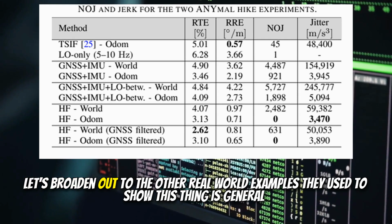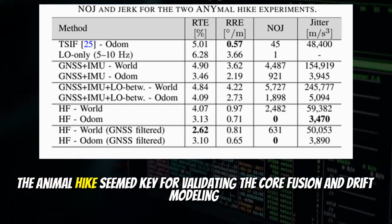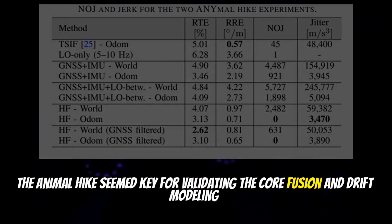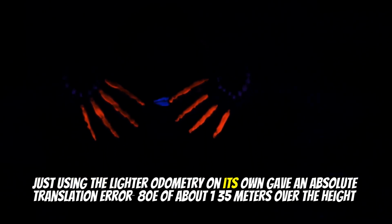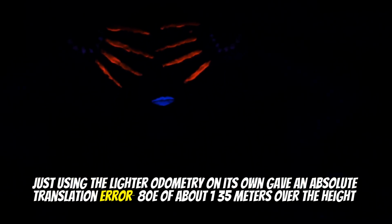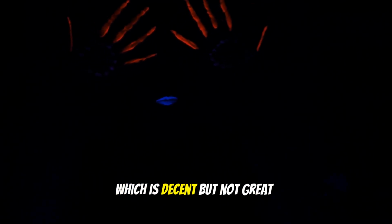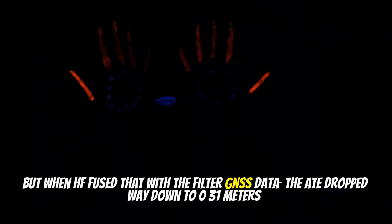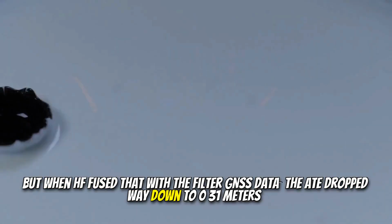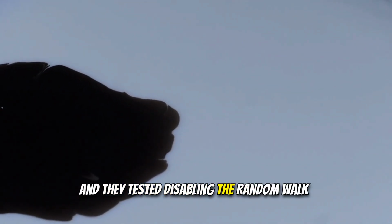Yeah. Let's broaden out to the other real-world examples they use to show this thing is general. The animal hike seemed key for validating the core fusion and drift modeling. Absolutely. Just using the LiDAR odometry on its own gave an absolute translation error, ATE, of about 1.35 meters over the hike. Which is decent, but not great. Right. But when HF fused that with the filtered GNSS data, the ATE dropped way down to 0.31 meters. That's a huge improvement. And they tested disabling the random walk.